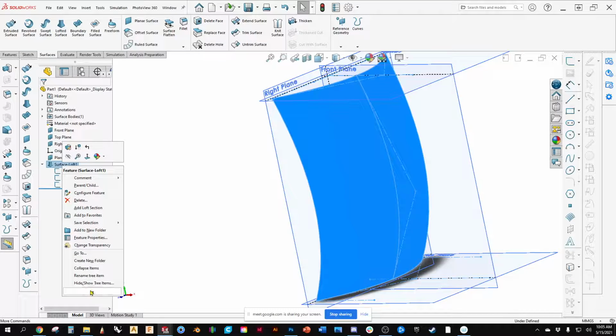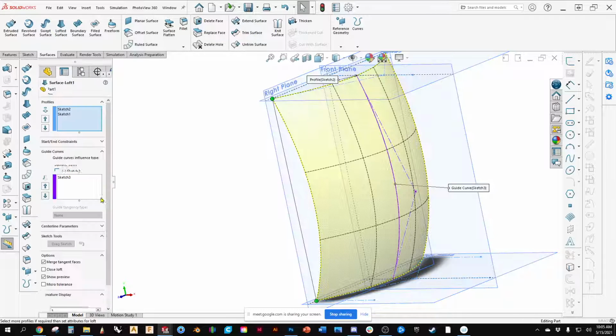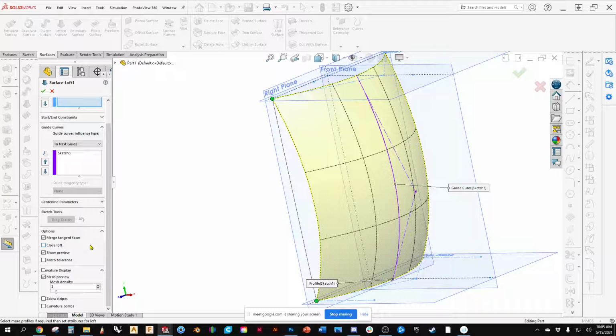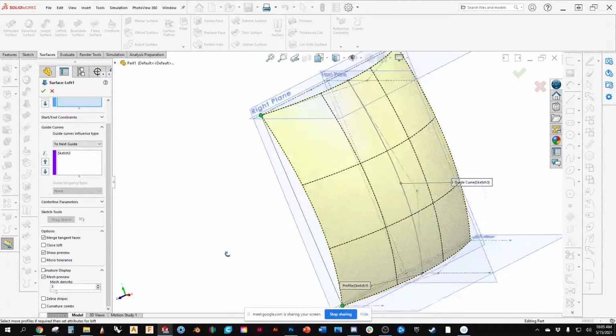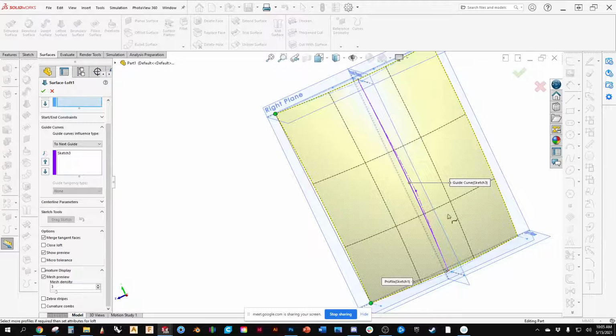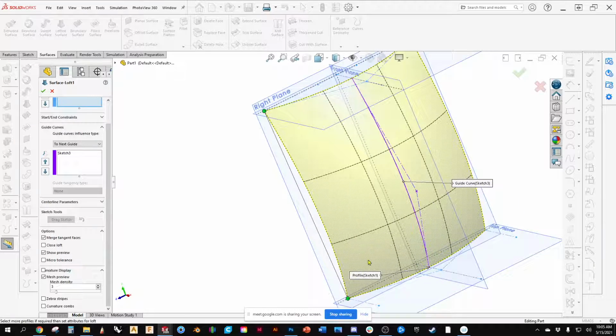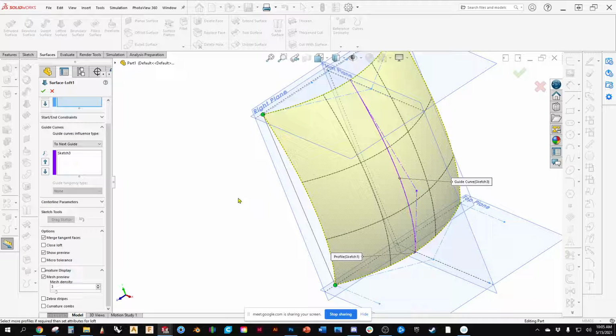And that is one of the key things, is that it gives you more control. It's always great to start with the age-old thing of the simplest surface, the cleanest surface. Well, sometimes the simplest surface doesn't work. It's kind of like we were talking about, using a 3-point spline is only going to give you so much control versus using a 5-point spline. But still, you can see I still have a nice clean grid for my surfaces, so it's still a clean surface because I'm only using really basic curves.